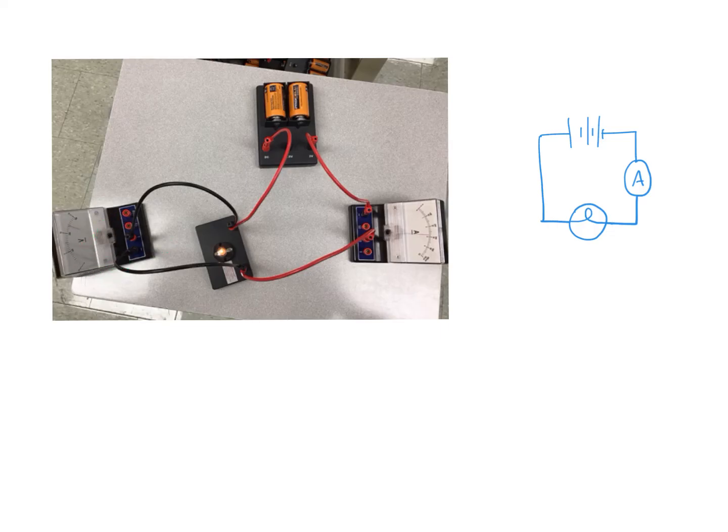Notice that the voltmeter is outside the circuit. It is connecting to the load outside the circuit, or in parallel, you might say. So notice that we've hooked this, right? These are the black leads right here, and this is the voltmeter here. You can tell it's a voltmeter because it has a V, okay? And the needle is moved over here because it's reading the voltage. It's reading the voltage drop across the bulb.